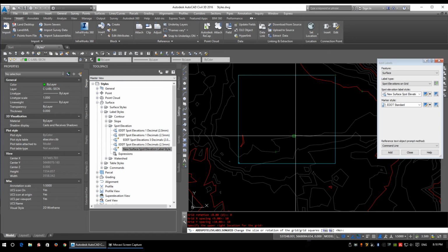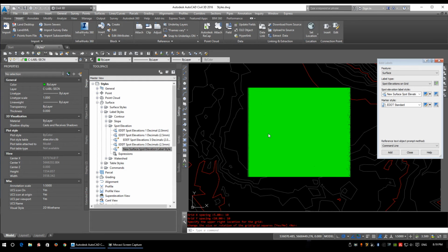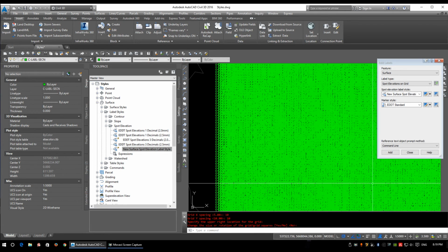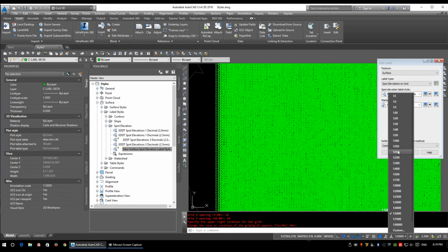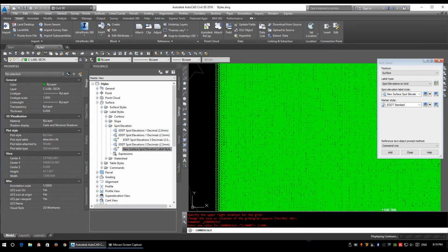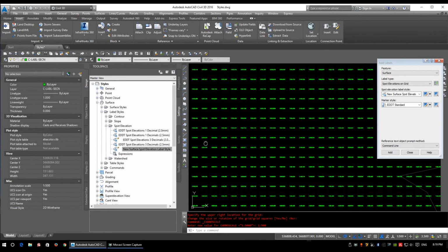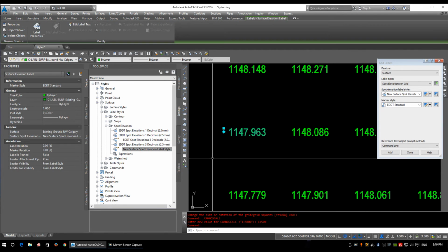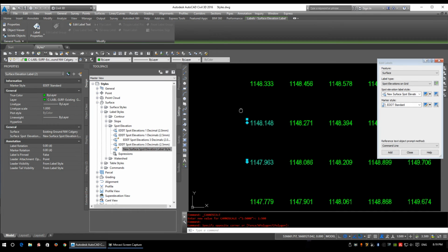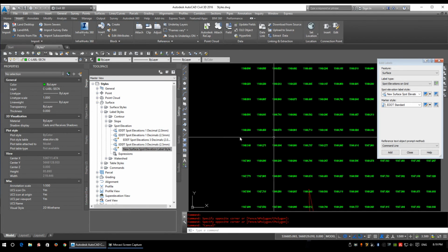And again, it gives you the option, do you want to modify anything? We'll just accept defaults, and give this a few minutes, as it could take time depending on how big your drawing is or how many points you're putting in. All right, that only took about a minute, and it gave me a bunch of laggy points. Now, the reason they appeared like this is they're showing the scale down here, so I'm going to switch this to 1 to 500, and we'll see what it looks like. And here the points are at 1 to 500. The grid has changed. Here's our point. And it's done a 10 by 10 grid.